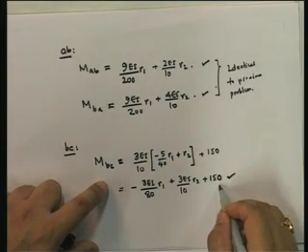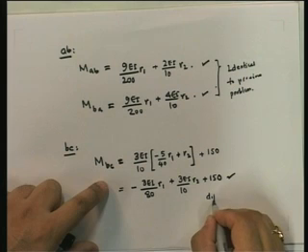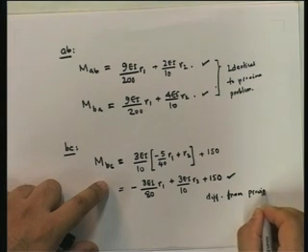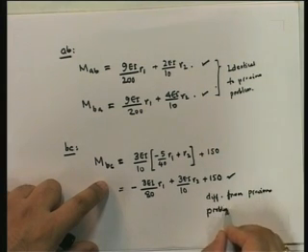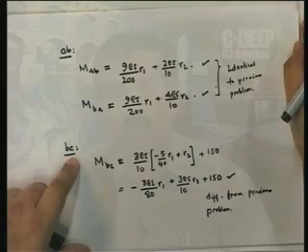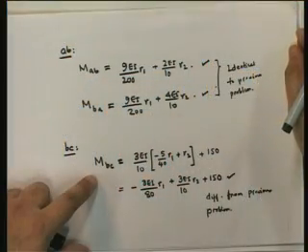Note that this relationship is different from the previous problem. Why? Because BC in the previous problem was a fixed member, whereas in this particular problem it has become a modified fixed hinge. Now, we've written MAB, MBA, MBC in terms of R1 and R2. What's our next step? Our next step is to write down the equilibrium equations, and for that we will take help of our virtual work principle, the principle of virtual displacement.